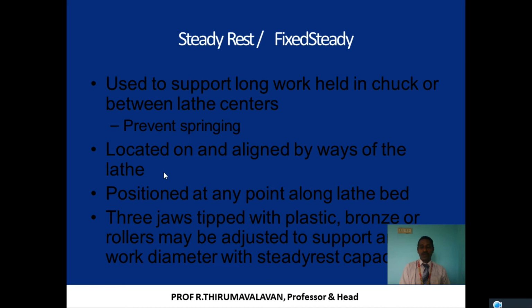Steady rest or the follow rest. Two types of rest are there, steady rest and follow rest. The steady rest we can name as a fixed rest, or fixed steady. Steady rest and fixed steady all have the same meaning. It is used for holding long workpieces, held on the chuck or between the centers, to prevent springing. Springing means sagging.